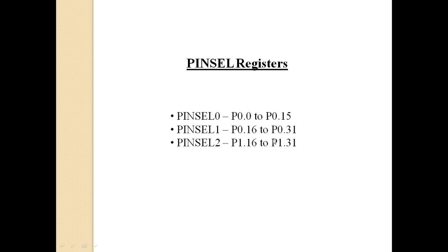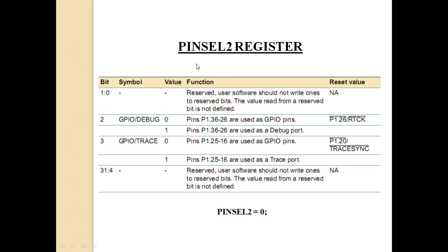In my case, I have connected LEDs to port 1.16 to 31. So I will be using PINSEL2 for configuring the functionality of port 1. This is the PINSEL2 register description. The register description shows what the functionalities of each pin are when you are configuring a particular bit, not pin, bit, of this SFR.